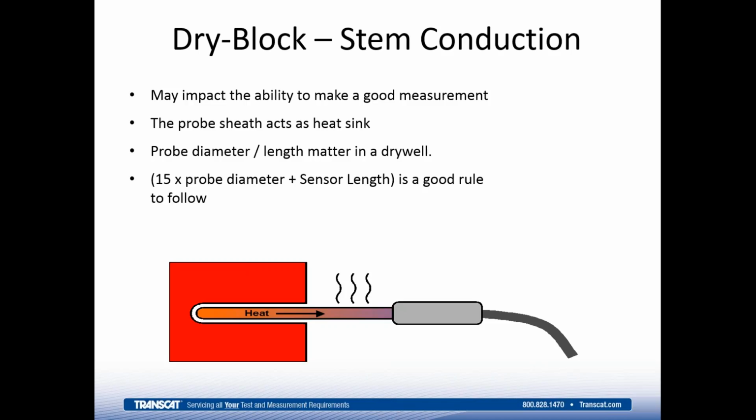That's going to be impacted by how well you are fitting, how close the diameter of the probe is to the diameter of the insert. So there shouldn't be too much of an air gap. In fact, we'll talk about how big that air gap will be. Other things that influence this stem conduction are the materials that the probe is made out of, and how thick the walls of the metal are of the probe sheath. Different things like that can affect it.